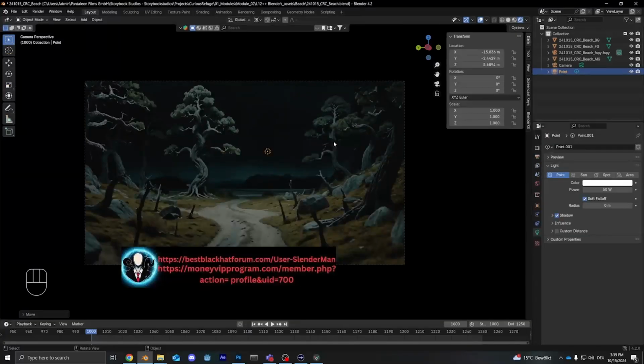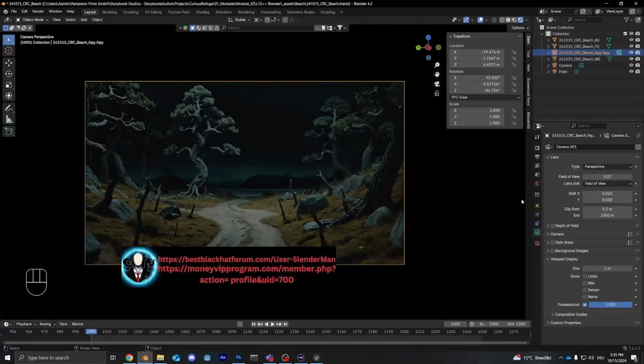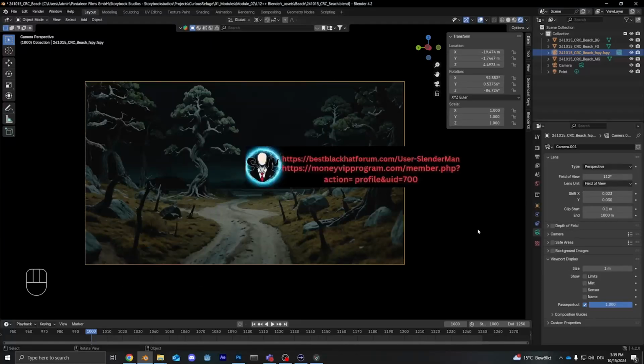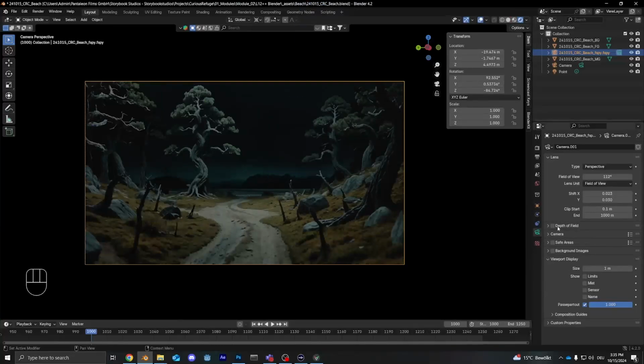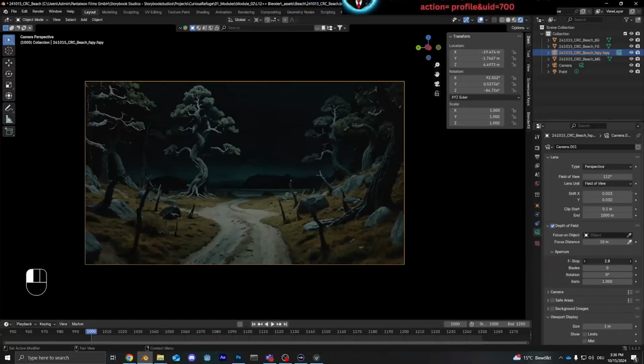One final thing I'd like to show you is, of course, we already kind of have this blurry effect in the scene, but that's not authentic, that's not real, because this was already in the generated image. Of course, in Blender, we can change that and have it render an actual depth of field as well, as I've already shown you. So make sure you have your new camera selected, click depth of field, and adjust the f-stop to something much lower, like 0.4, for example. And then you can either create a focus object like I showed you, or just pick the focus distance. Now you have a really nice little miniature look like this.